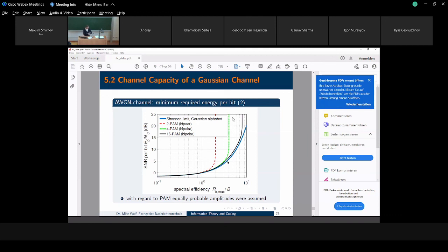And now, and then we finish, because this is communications engineering to a large extent. Let's say in the real world, we don't want to transmit with Gaussian distributed amplitudes, because this is hard to achieve. Let's say we start with just binary transmission. So we only use 2 amplitudes at the transmitter. This means our mutual information per symbol can never be larger than 1 bit because we have only 2 symbol states at the transmitter.